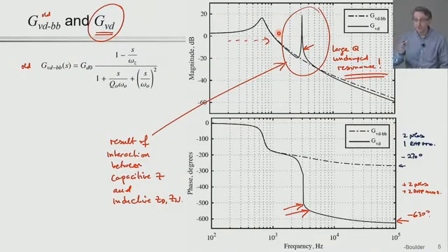Practically speaking, remember, C1 is a part of a converter. You cannot arbitrarily reduce the value of C1 because then you're going to have increasing ripple across that C1. You will then be facing the issue of whether you can find a component that has such a small value and enough current rating in terms of the RMS current and so on.